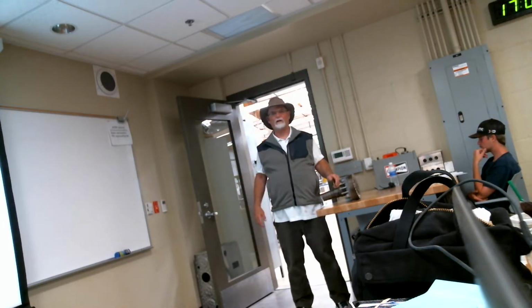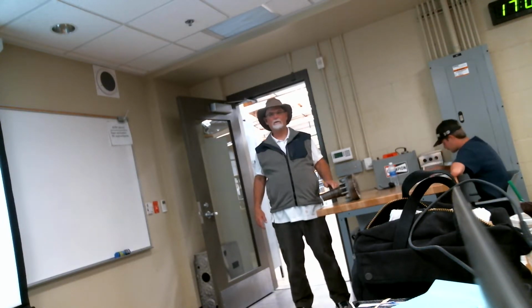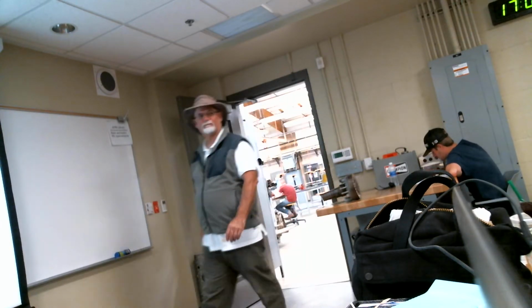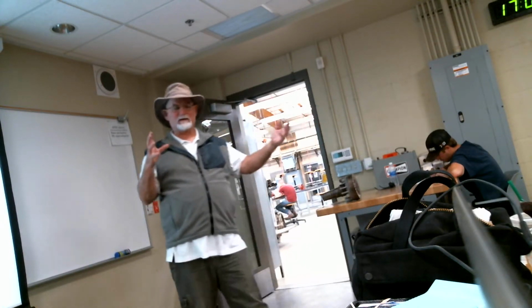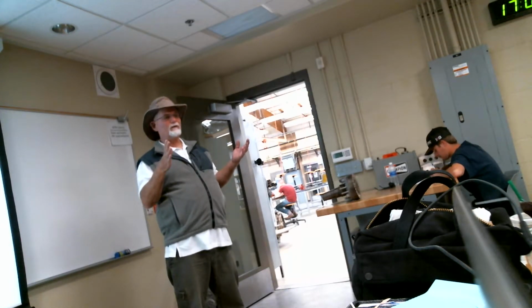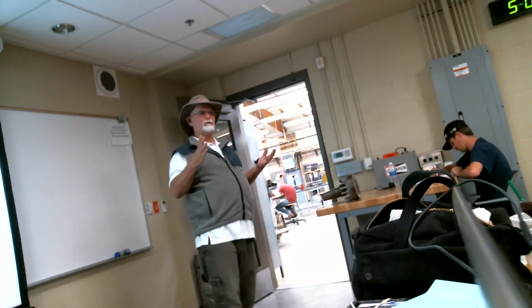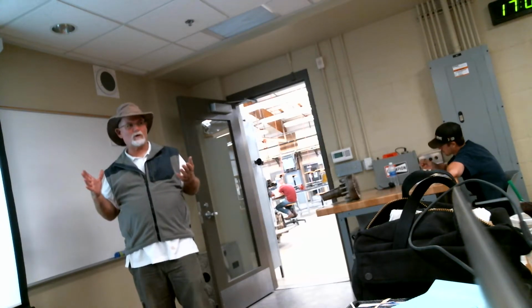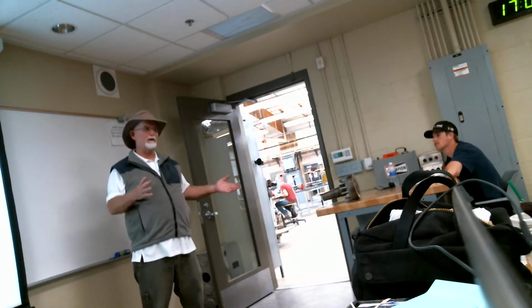Okay, so that principle that we said, that the load in a circuit will always match the input until something fries. In other words, like a transformer. A transformer sends energy through. If I don't have the other end of the transformer connected to anything, because of inductive reactance, the primary side of the transformer becomes infinitely resistant, and the current almost comes to a stop. So a transformer at idle uses almost no current, even though it's a dead short in the AC circuit. Same thing is true here.